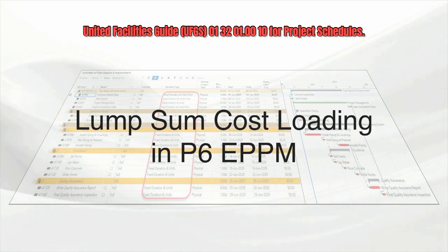The SDEF format is particular and requires fixed-price cost loading using a lump sum labor resource. This lump sum labor resource cost loading approach is also written in the Unified Facilities Guide Specifications, UFGS, for project schedules, specifically in the Primavera P6 mandatory requirements section. These UFGS specifications are a joint effort of the USACE, the Naval Facilities Engineering Systems Command, and the Air Force Civil Engineer Center. Before September 30, 2023, NASA also was included in the UFGS combined effort.